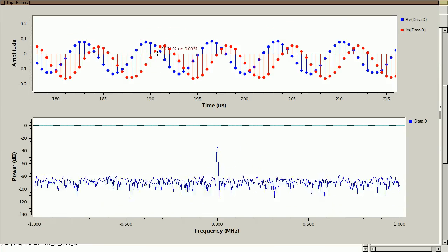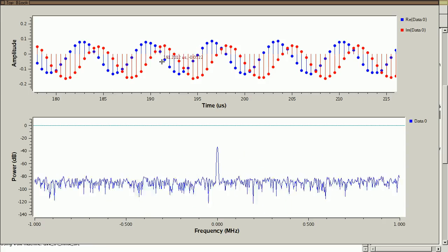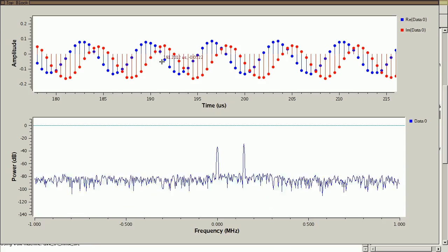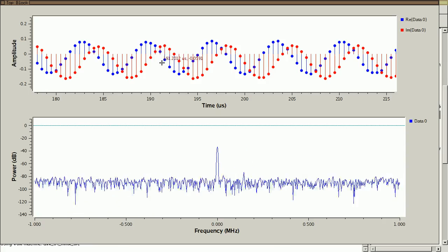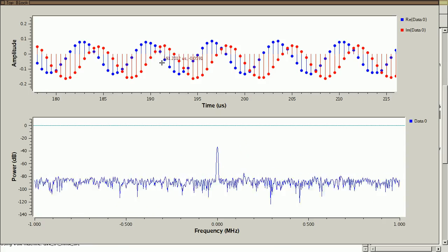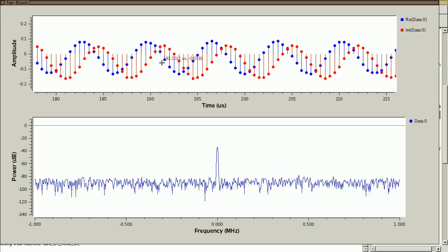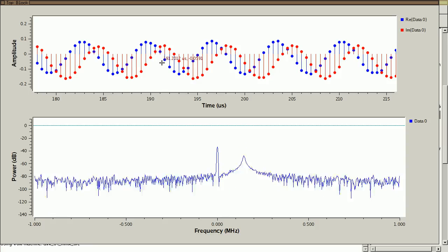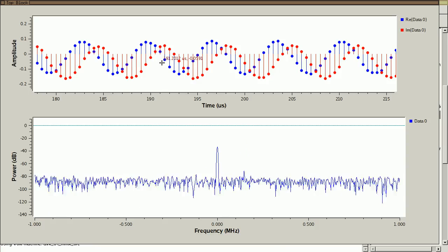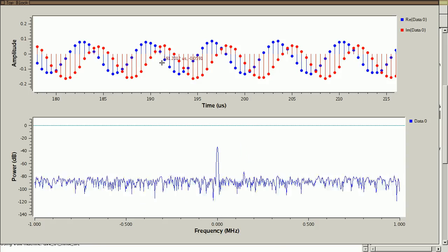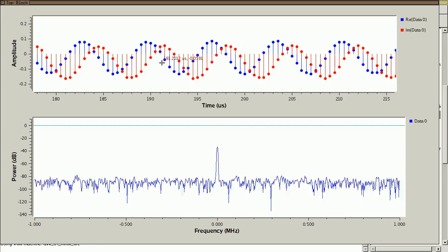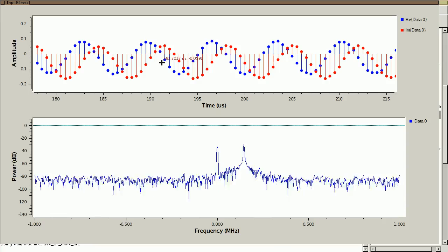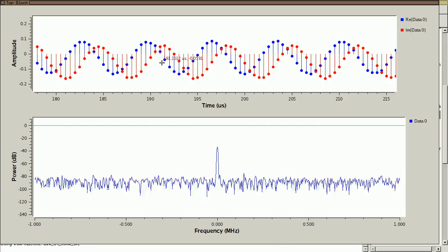The amplitude is fairly small if you think of maximum amplitude being between negative 1 and positive 1. That's the scale that we expect, because when the Osmocom source receives information from the HackRF, it takes these 8-bit values and then scales them and assigns them floating point values that are between negative 1 and 1.